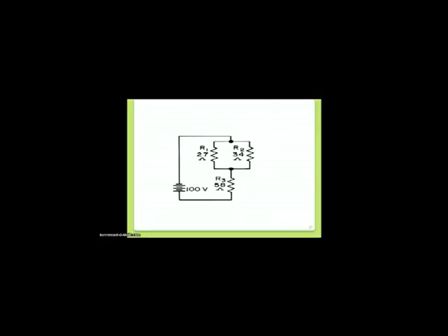Now, in a series parallel network, we often have to do more analysis, like finding many currents and many voltages. So here we can see there is a total current. The total current gets divided because there is a parallel branch, and at the other junction the branch currents again combine together to get back the original total current.